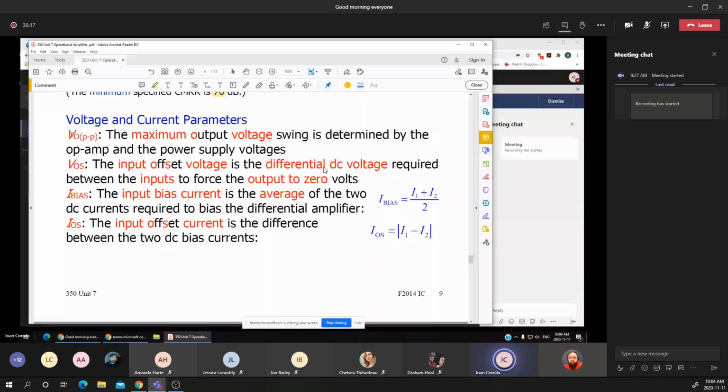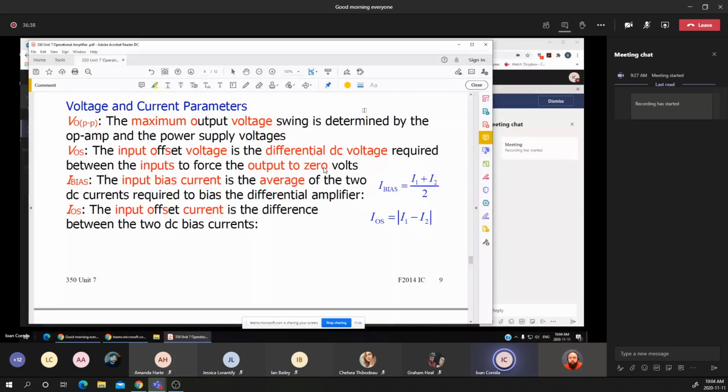And remember that the output voltage is actually based on the supplied voltage less 1 or 2 volts in this range, just to give you an approximation of the output voltage, which is defined by the op amp and by the supplied voltage to the circuit.